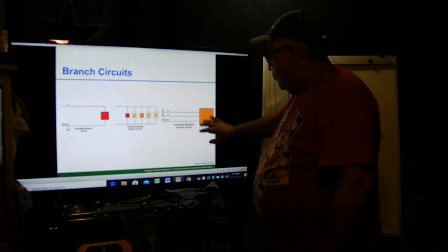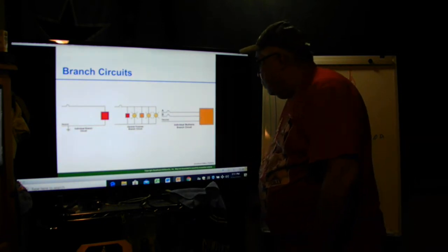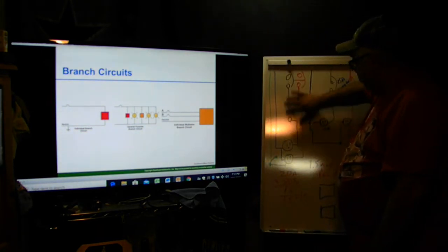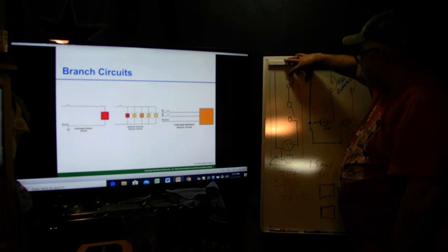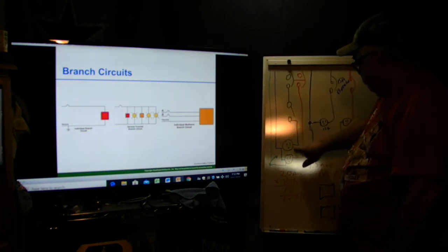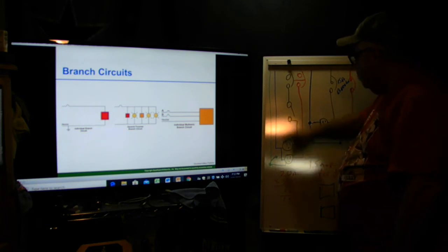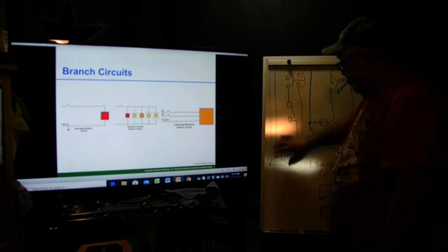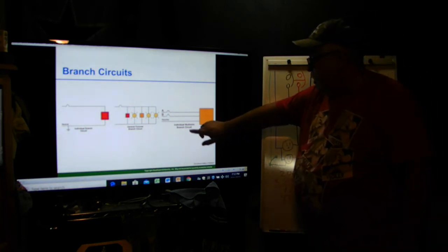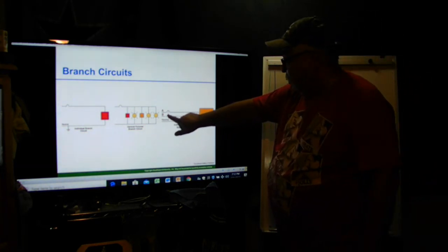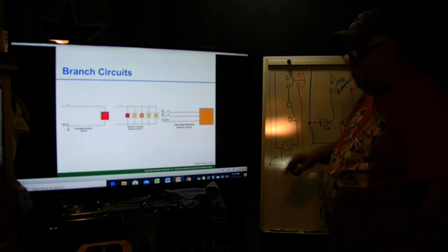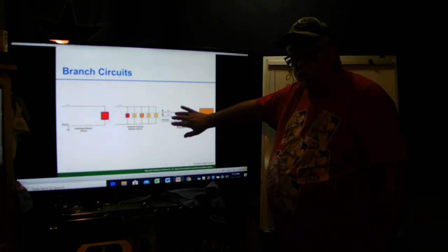And then this one over here, individual multi-wire branch circuit. It's this drawing right here. So I got 2 hots coming down. One of them is switched going to one receptacle, the other one is hot going to the other. I have my neutral coming down, and then here's my ground. If you notice, it's got a bar across right here, just as I got mine. I just made mine solid. So that means this would have to be a 2-pole breaker.